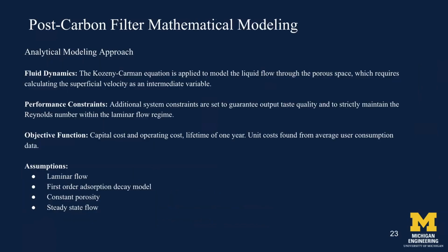To build our analytical model, we utilize the Kozeny-Carman equation to simulate the flow dynamics. We set performance constraints to guarantee output taste quality and to strictly maintain the flow's Reynolds number within a nominal flow region. Our model relies on a few key assumptions. The flow is laminar and steady state. The carbon has a consistent porosity, and the filtration follows the first-order decay model assumption.